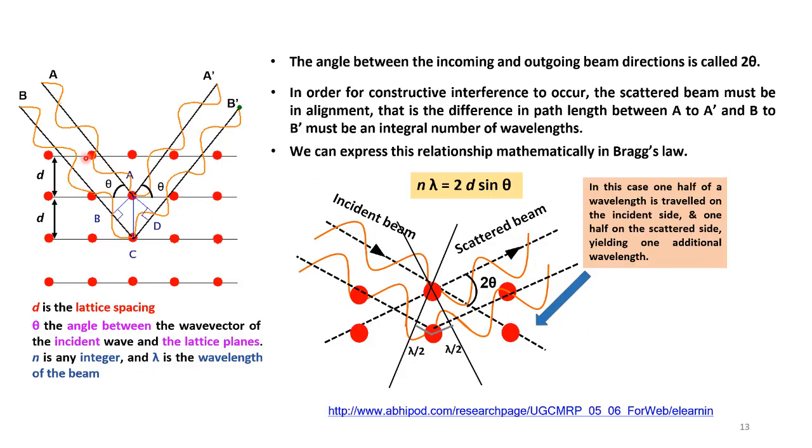So here, suppose this is a simple cubic structure, and there are multiple planes like this, and these planes are separated by a distance d. From here, we can calculate the distance d between the two planes. We know the lambda we are bombarding onto the sample, because the lambda is fixed for an X-ray diffraction machine, and n should be an integer.